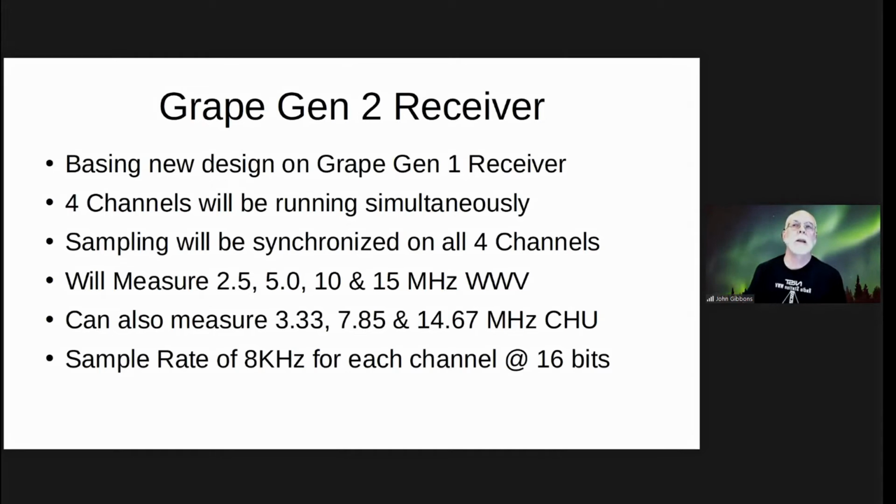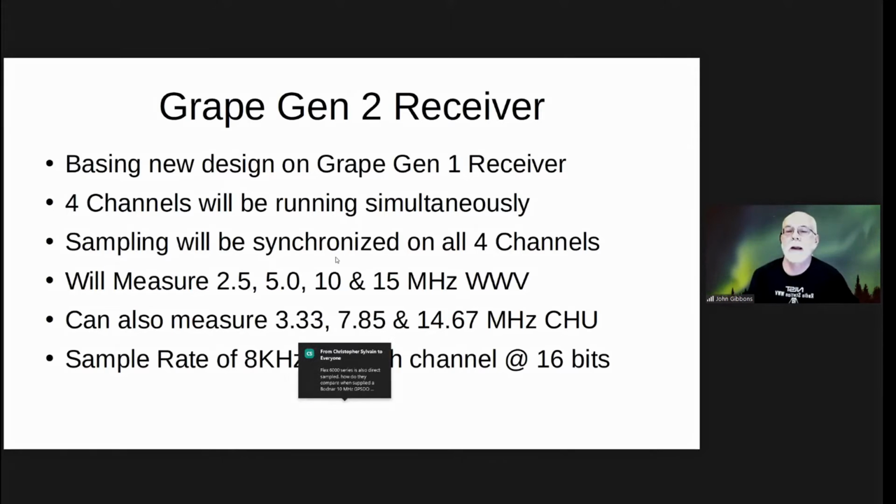And it gave us the target. We were trying to accurately measure the Doppler shift to 1 millihertz of deviation, which on a 10 megahertz signal, 10 to the 7 hertz, with 1 millihertz, is a 10 to the minus 11 sensitivity. So it's down to 10 to the minus 10th from that. So we are using that design to move forward since it has worked.